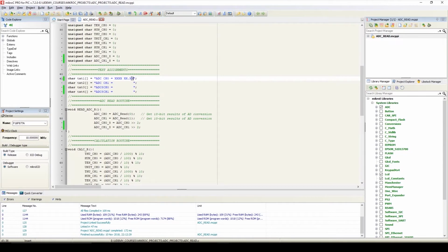So in this case we'll print the letter V on 20th column of LCD display, decimal place digit of the voltages at column 19 and decimal at place 18, and 2 significant digit of the voltages, that is unit place and 10 place, on column 17 and 16. Now I'll perform some calculations to convert the raw data into voltages, and we'll also modify the print routine, and